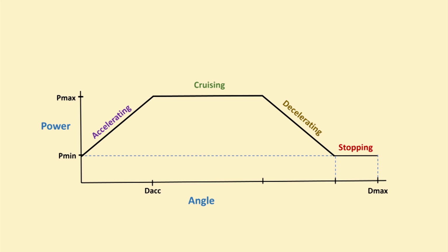This Turn-In-Place MyBlock uses my team's acceleration MyBlock. Using acceleration, the robot starts at minimum power, P-min, and gradually increases its power until it has turned distance deceleration when it is at maximum power, P-max. Then, it stays at maximum power until it starts to slow down. When it gets to minimum power again, it stays at P-min for turning angle D-brake until it gets to the